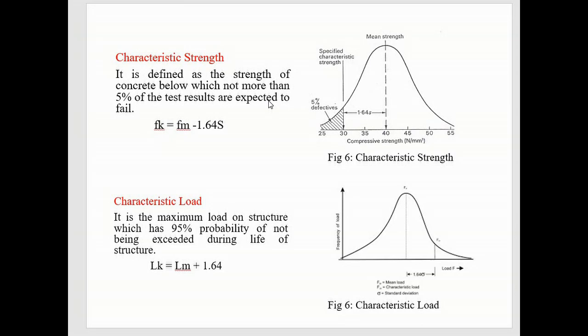I will repeat once again. For example, if we consider 100 cubes of M20 concrete blocks, and we test all the 100 cubes, only 5 cubes are expected to fail. But all other 95 cubes are expected to reach the expected value of M20 concrete.